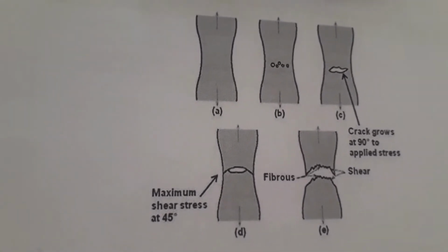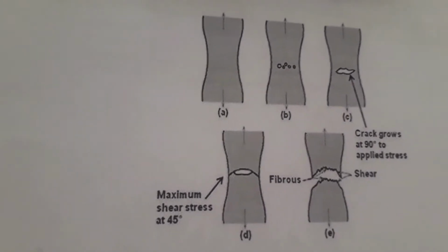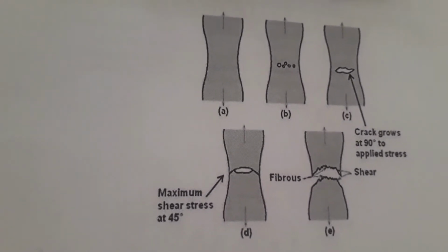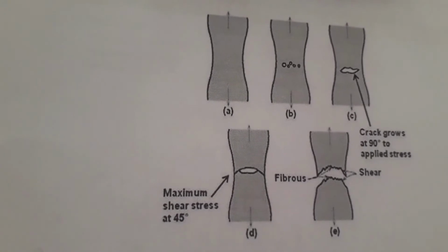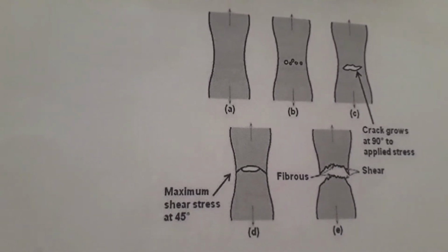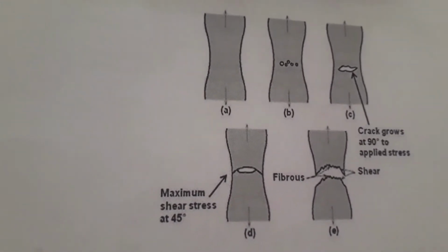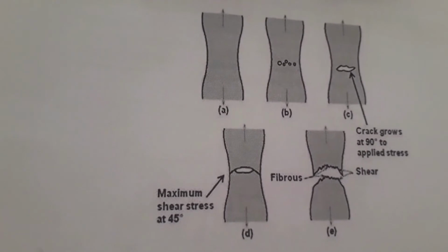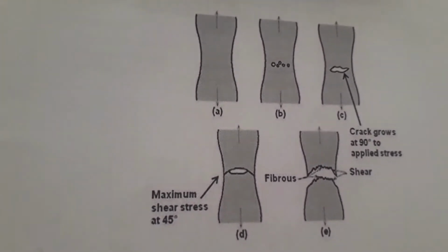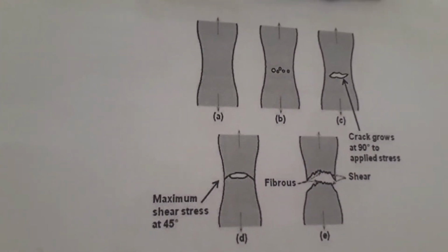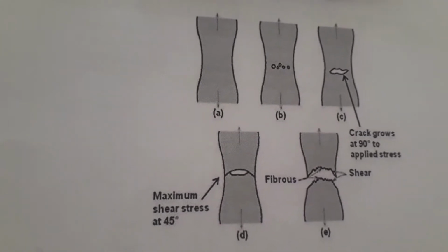The new fracture surface has an irregular appearance. The final shearing of the specimen produces a cup type shape on one fracture surface and a cone type on the adjacent fracture surface. The central interior region has an irregular and fibrous appearance, which signifies plastic deformation in the material.